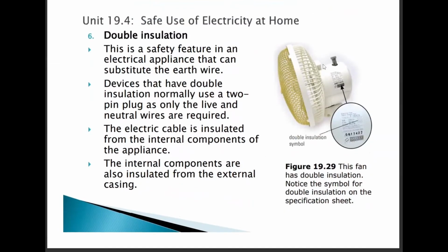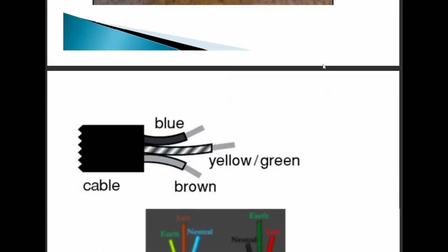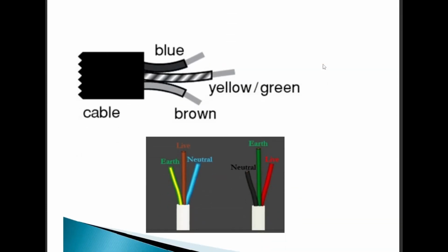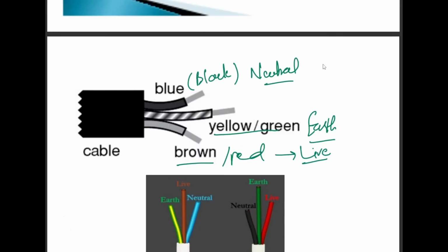So you can see this is a double insulation using a plastic body over metal appliances. Okay. This color code was a part of the course previously, but now it's not. But I recommend remembering this as general knowledge. In real life, the yellow-green wire, the yellow wire or the green wire, is the earth wire, universally. And the brown or the red wire is usually the live wire, as a sign of danger. The blue and the black wire are usually the neutral wire, right? So wherever you go, this is what every engineer or mechanic follows.